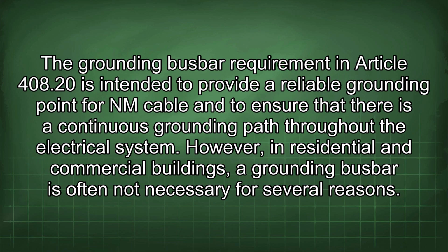The grounding busbar requirement in Article 408.20 is intended to provide a reliable grounding point for NM cable and to ensure that there is a continuous grounding path throughout the electrical system. However, in residential and commercial buildings, a grounding busbar is often not necessary for several reasons.